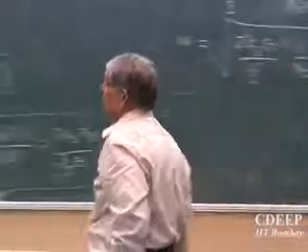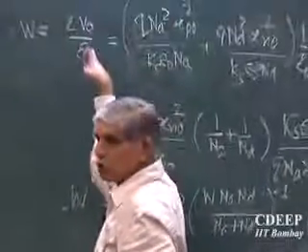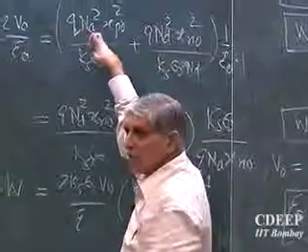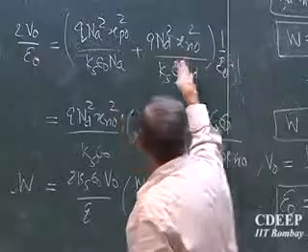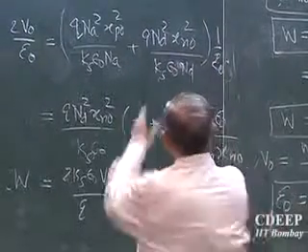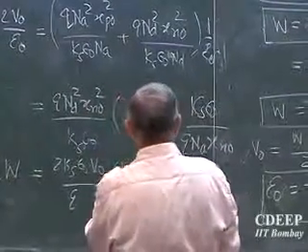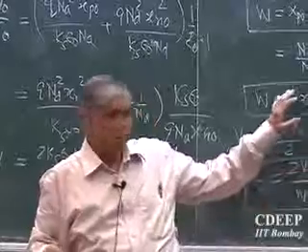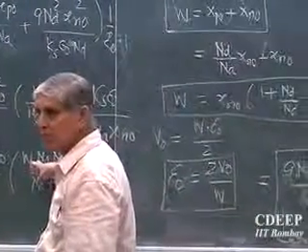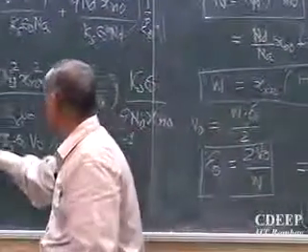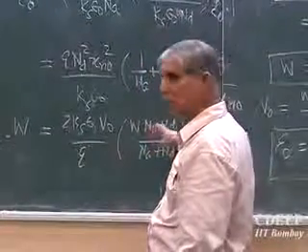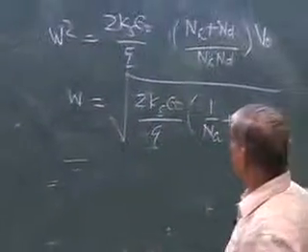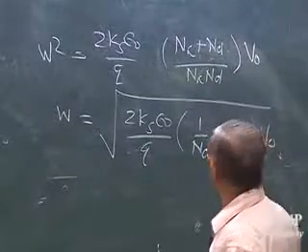What I did is I wrote W is equal to 2V0 by E0. V0 I took that expression which I derived, that was only Na, so I made Na square by Na and Nd square by Nd. I write 1 upon E0 by this term, collected the term, this I took out. This term will then become from W relationship in this form, replace XNO by this from XNO from here, so I'll get in terms of W that value. So I get this expression, W is equal to twice k epsilon naught V0 by Q into W Na Nd, Na plus Nd to the power minus 1 upon that. If I collect W, I get W square is twice k epsilon 0 by Q, Na plus Nd upon Na Nd into V0.